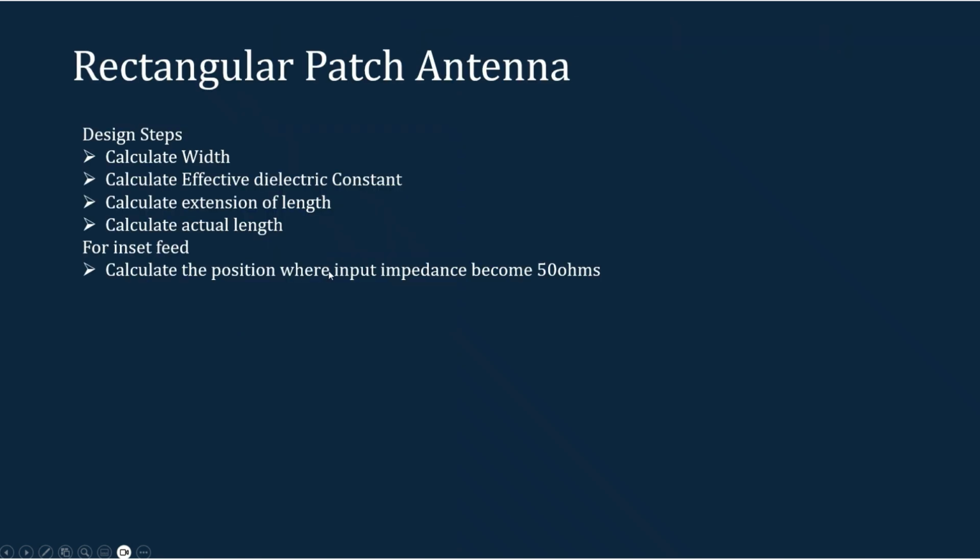This is the design step for the rectangular patch antenna. First you have to calculate the width, then the effective dielectric constant, then the extension length, then the actual length, then the inset feed positions. In our simulation video, let's see how you can utilize these steps.